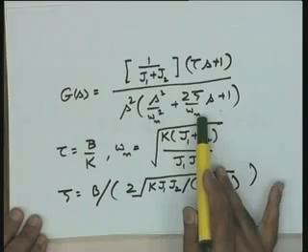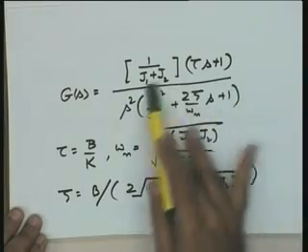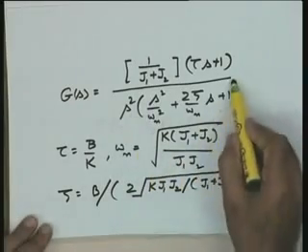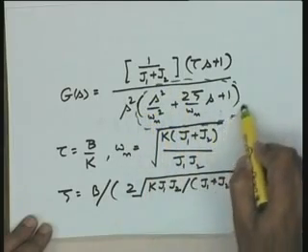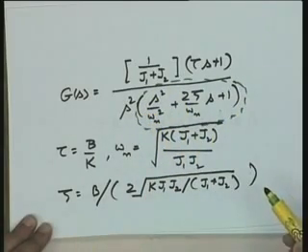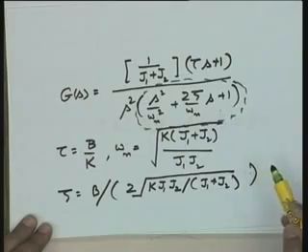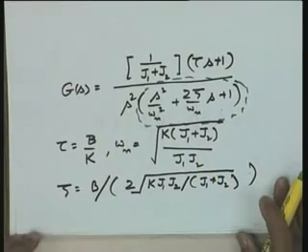You can just look at the result, elimination of the variable theta 1 and rearrangement in the standard form of quadratic lag. You will recall this second order term is a standard quadratic lag. So, rearranging the equation in the quadratic lag gives me this result.